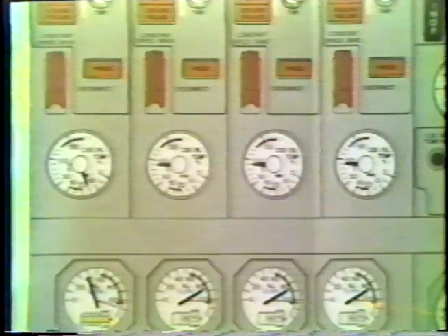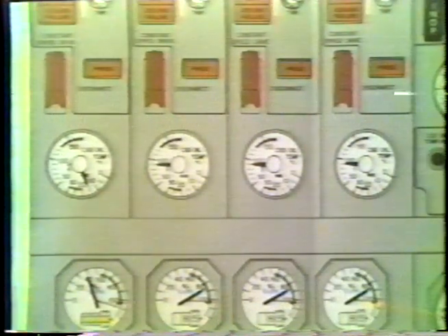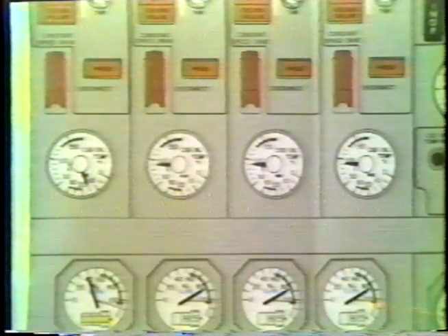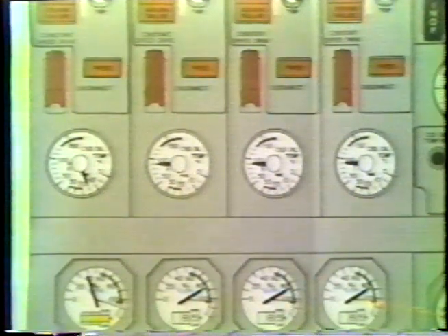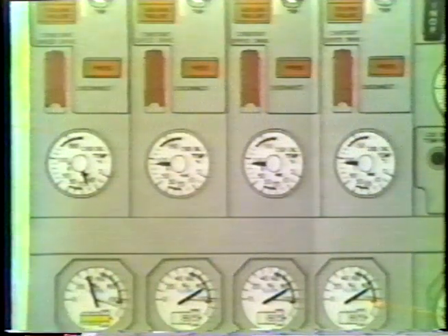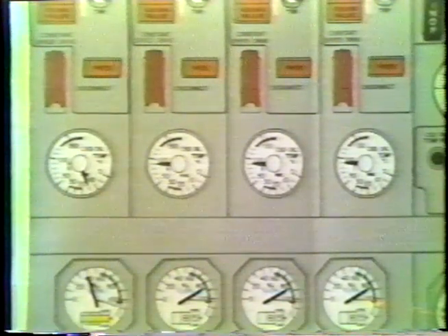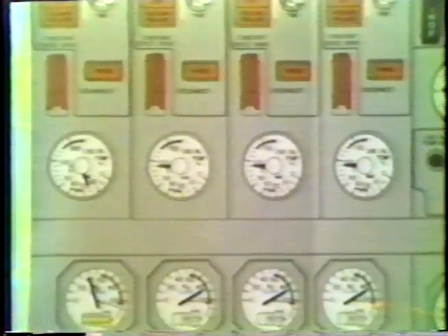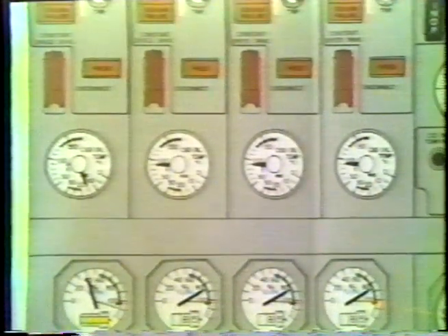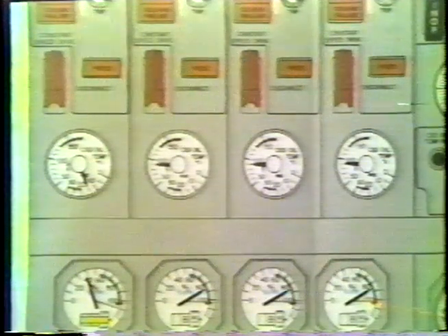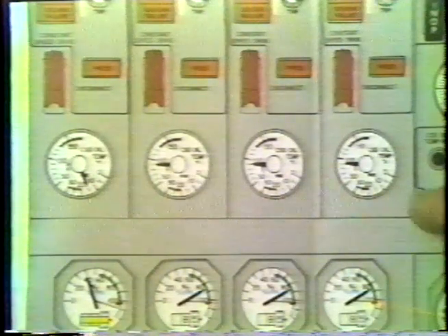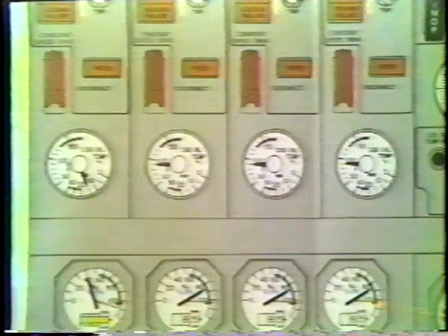Two things could cause these temperatures to read abnormal. One is a low oil quantity. A low oil quantity would make the oil circulate faster, not have enough time in the cooling radiator, and make it operate at a higher temperature. Two, the internal operation of the CSD itself, either through mechanical or hydraulic operation, excessive clearances and so forth, could make it work much harder than is necessary to operate the CSD.